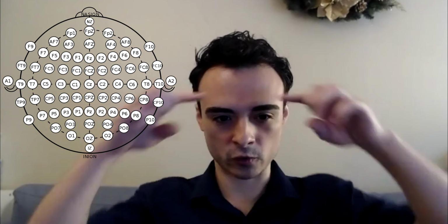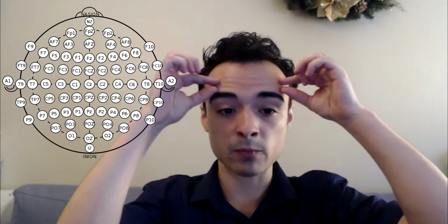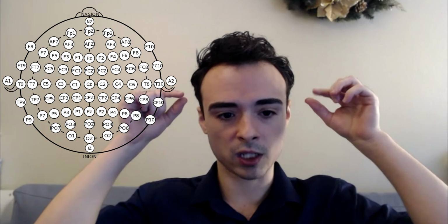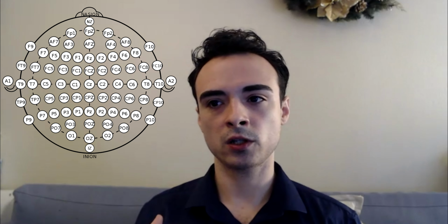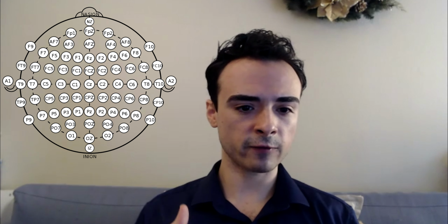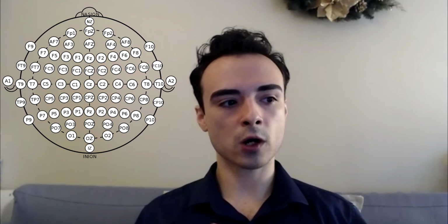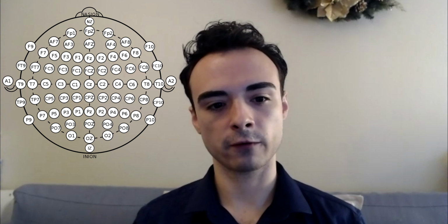Muse's frontal electrodes are technically AF7 and AF8, right? That's what they're listed as. But typically, they're almost always worn in the FP1 and FP2 position, which is right above the eyes. That's where the headbands typically sit, and you don't have much ability on the Muse 1 or 2 to alter that, compared to the Muse S, where my electrodes actually sit more flush with my hairline, which is much closer to the intended AF7, AF8. So from that perspective, it's more comfortable, and also more comfortable in actually getting the electrodes that it's advertised and getting. And so for me, I tend to gravitate towards the S over the 2 in terms of just pure usability.